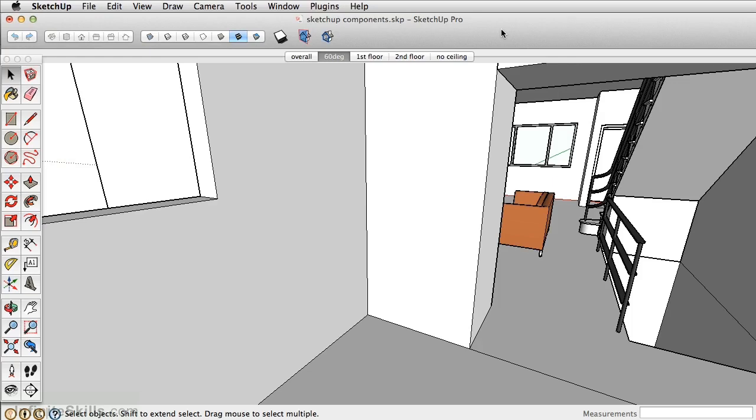In this chapter, we're going to look at a great feature in SketchUp called New Match Photo. It allows you to take an existing photograph and turn it into a SketchUp model based off of the vanishing points and the axes of a photograph. We'll walk through how to set up a new match photo, as well as import and create a china cabinet and drop it into the model.